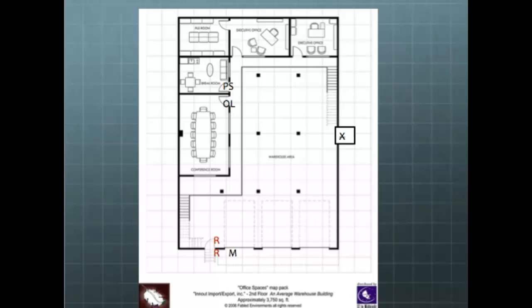I put an office lock on the conference room. I could have put a passage set there because the conference room could be open to anybody. I could have put a classroom security lock there if I thought about that as the safe room. If there was a shooter in the building, everybody run, get in the conference room, and close the door, and it stays locked. I mean, you could put a storeroom lock if you wanted to on there, I guess.